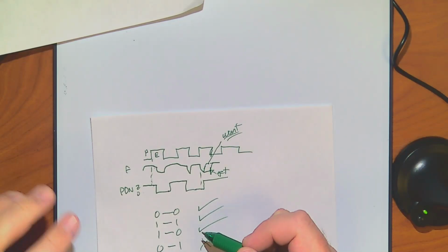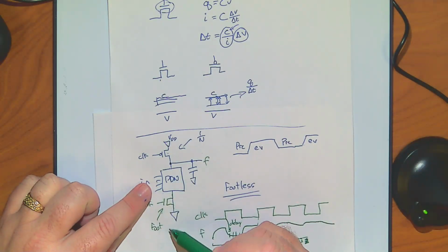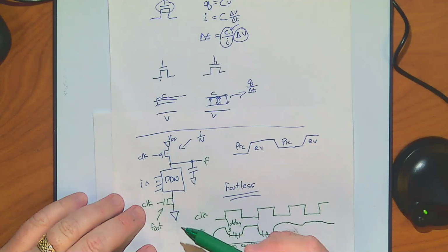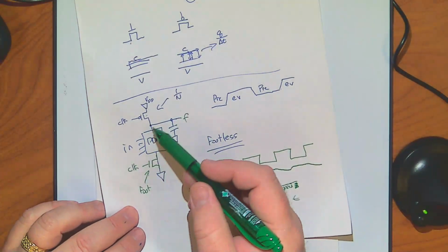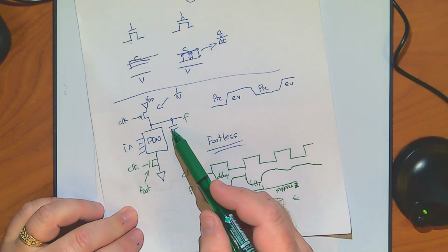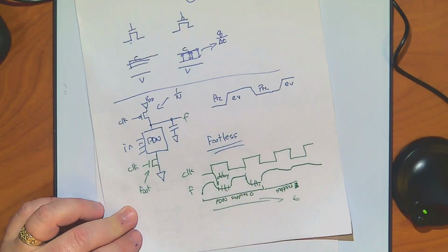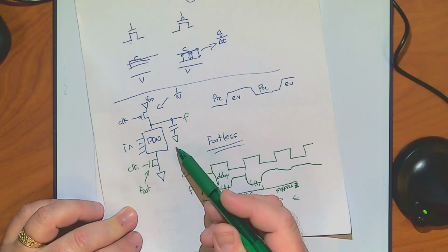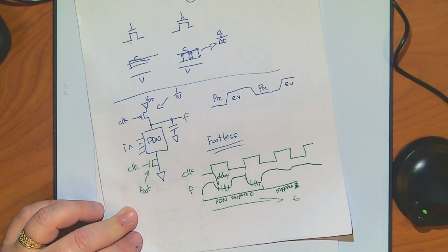Now, the majority of your gates in your pull-down network, if an input is 1, it's generally going to tend to connect it, turn it on, right? Now, if I were to cascade these things, one of these to the next one, initially, this capacitor is charged, so it'll supply a 1, which means it'll discharge this, or cause the next stage to discharge, and then it's all over with.